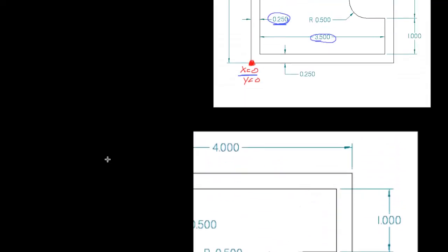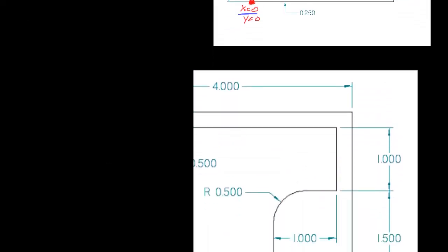Okay. So let's take a look at this point right here. Here's point D. Cutter location there, so that's point D. And then I know that I want to use an arc to go around this sharp corner. And to make a sharp corner, I basically ride around this corner always. So the tool is always in contact with this part. So the tool is going to end up right there.